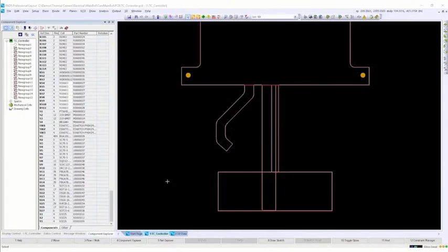Real quick before we move on, I did want to mention some basic fabrication capabilities of Flex Design that are probably more common with most manufacturers out there. The polyimide materials you're using can range anywhere from 0.5 mil up to, like I said, 5 millimeters. Copper on Flex can range anywhere from 1/8 ounce up to 3 ounces. And your adhesives are generally so thin that you typically don't have to take those into account.